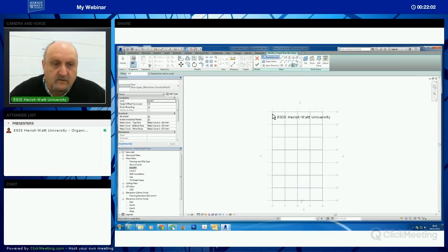And I want it to be offset beyond the columns by some value, usually 250mm, but that can vary, and I need you to keep your eye on that if it stays at 250. So it's rectangular, so I'm just going to use the rectangular tool.